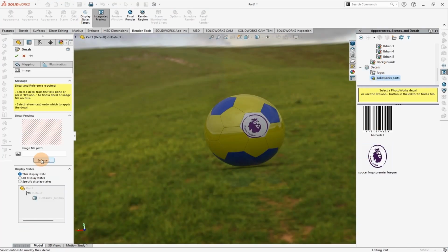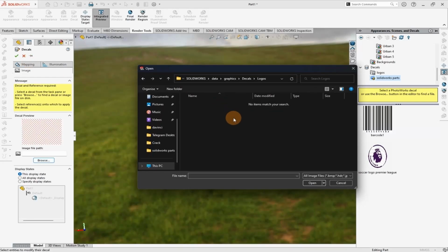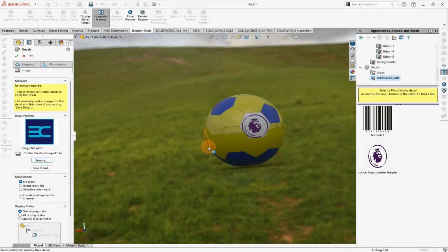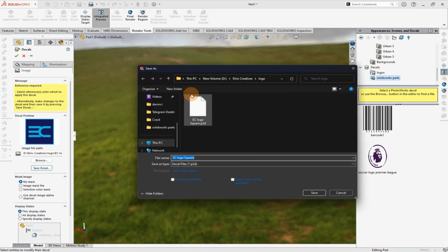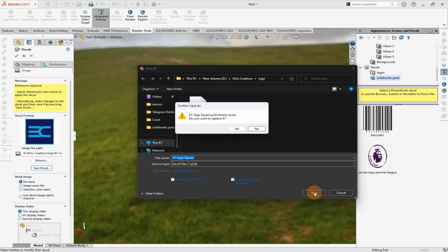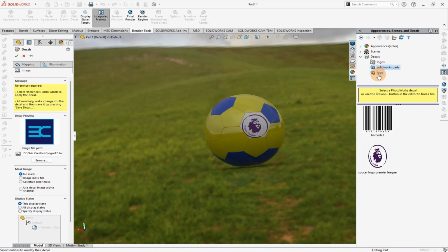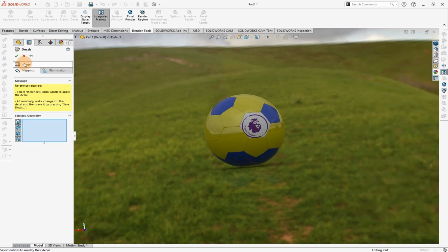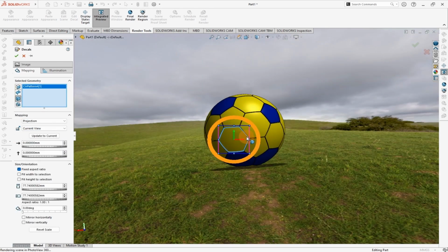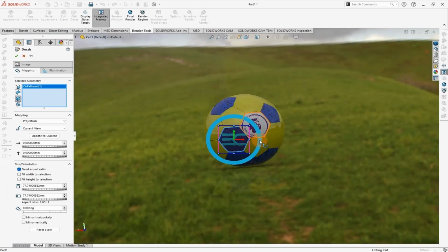We can also add logo from our library. I can have my logo there, so just say yes. This will add the logo to the display here. Then now I can select mapping. Then here ensure the body is selected, not all this one, but just select the body only. Then I can click that part to map the logo there.